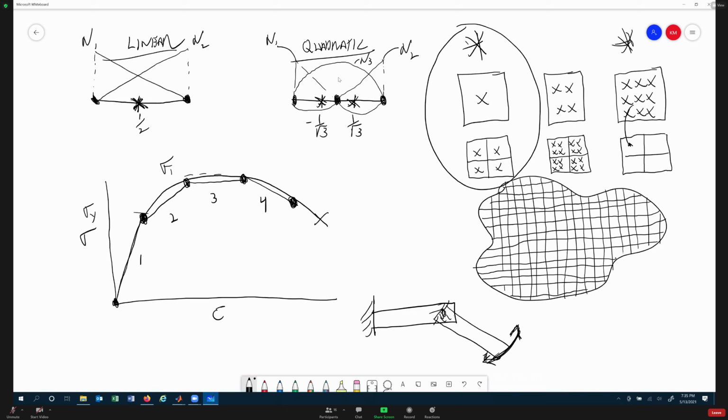Solve it with something that's quick and easy to say, are my boundary conditions right? Am I getting results that seem reasonable? Are the high stresses in the areas where I should be getting high stresses? And then once you've done that and you need more fidelity, start heading this direction to get better refinement in your results.